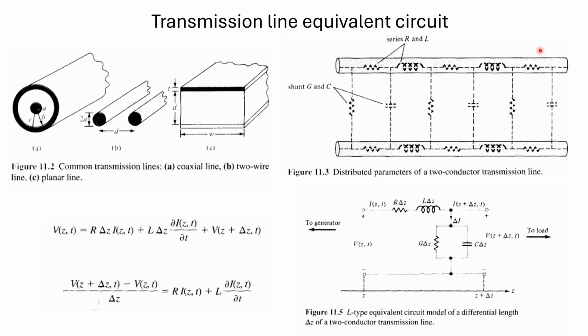This is the example of the two conductor parallel lines. So how can we draw the equivalent circuit? The electrical equivalent circuit has the resistance, inductance, and then again resistance, inductance, in series, and in parallel conductance and capacitance, again parallel conductance, capacitance. So this is the equivalent circuit for the two wire conductors.